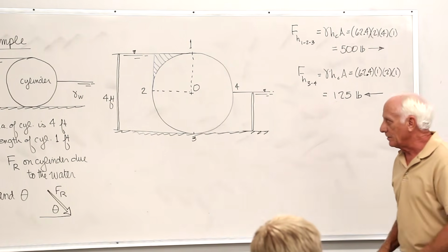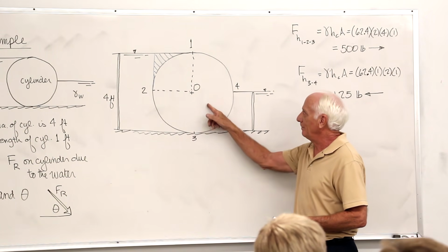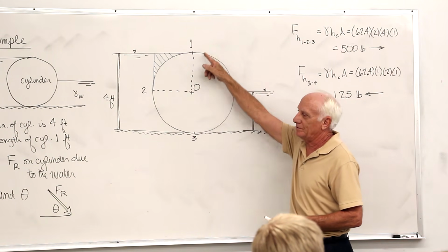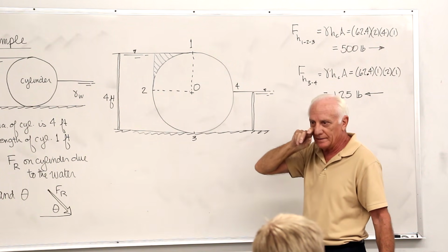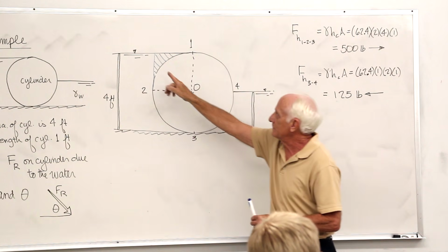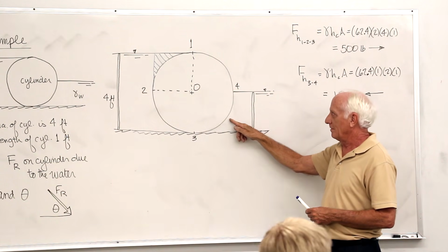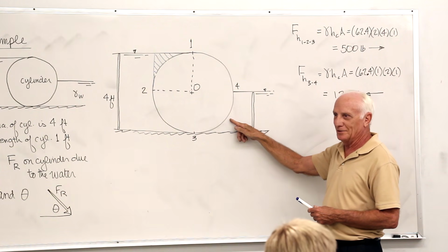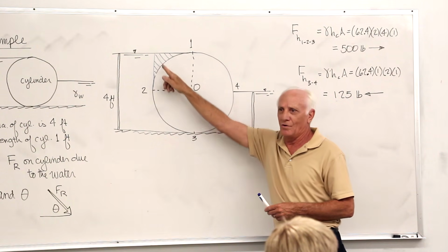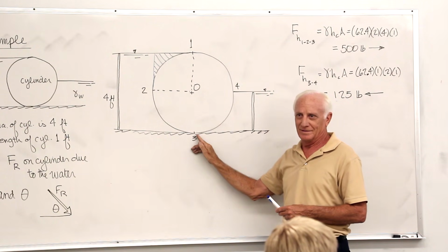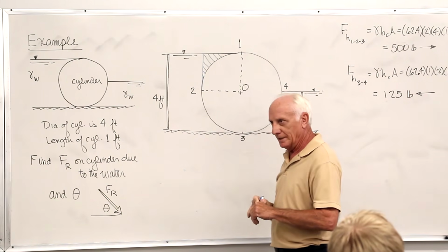Extend the ends of that curved surface up to the free surface. Now, if I go up, there's no free surface there. Well, you saw my comment in parentheses. Real or imaginary? You pretend there's a free surface there. Is it this free surface or is it this free surface? Well, look at my finger. Which one can I go to in the same fluid? This one. Can I go under here and squeeze through there and go up there? No, it's closed down there. So I go to this free surface. There's the free surface. Is it real? No, it's imaginary.